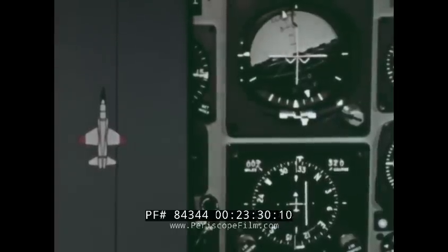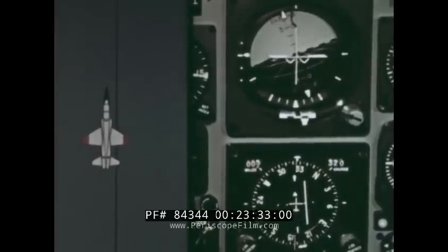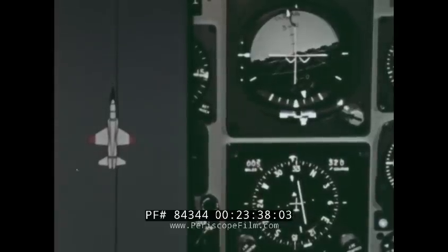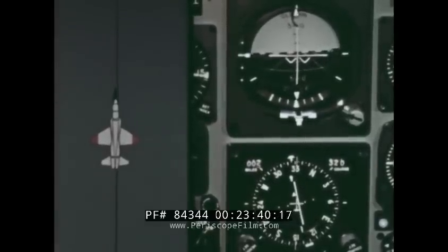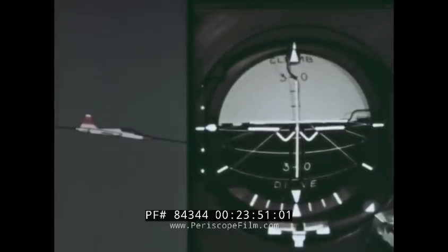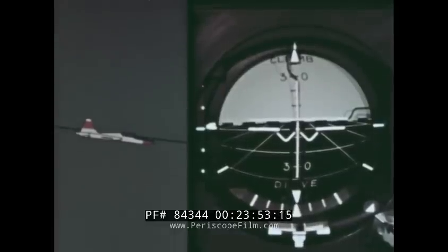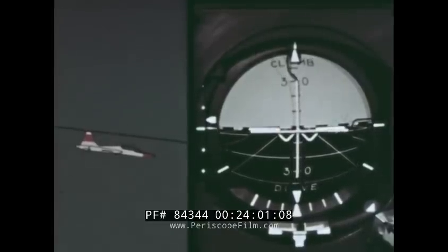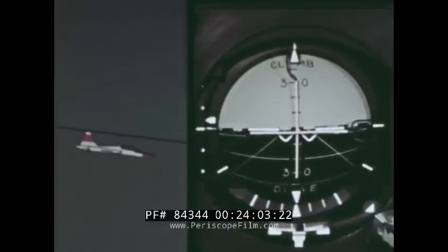Bank right until the bank steering bar is centered. Keeping this bar centered will steer you back to course. The other pair of indicators, the glide slope indicator and the pitch steering bar, give you the same type of information, only in pitch. For instance, if you drift below center line, the two indicators will move above center, and you'll increase your pitch attitude to center the pitch steering bar. As you approach the glide slope, the indicator will move to center.